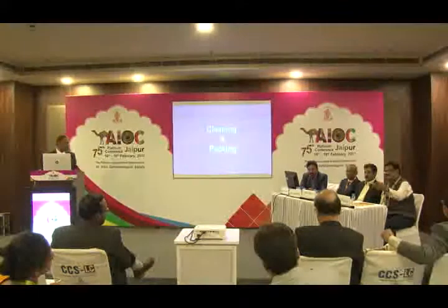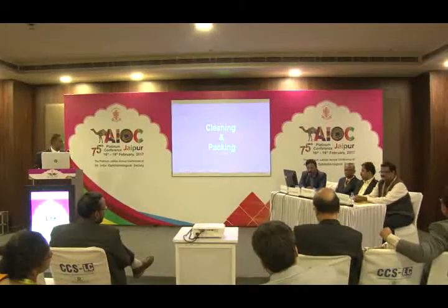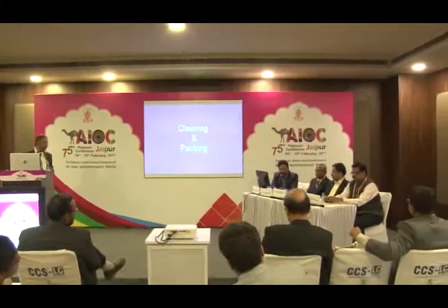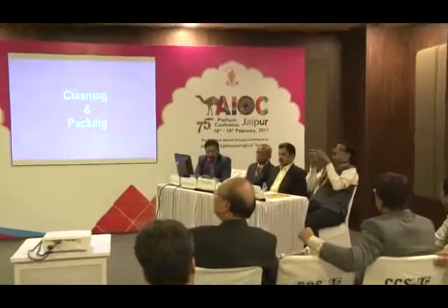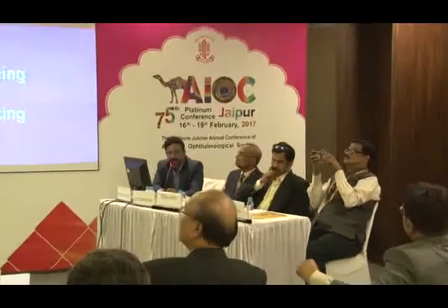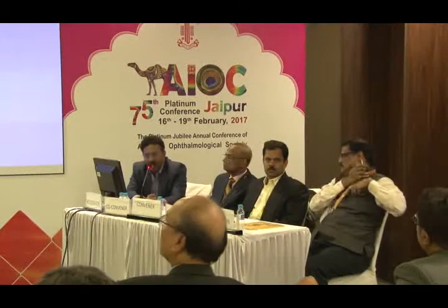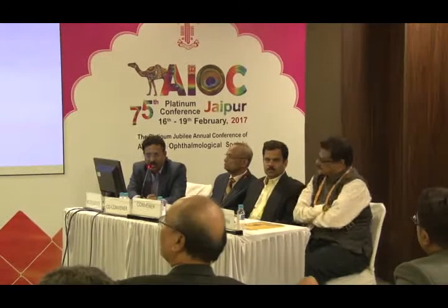So if a team is operating, after 30 to 45 minutes, the air quality changes with your exhaled and inhaled air, as well as the debris given out by the surgical team as well as from the patient's skin. So this is a reality. That's the reason why ventilation standards are coming up. So you need to properly ventilate the operating room.